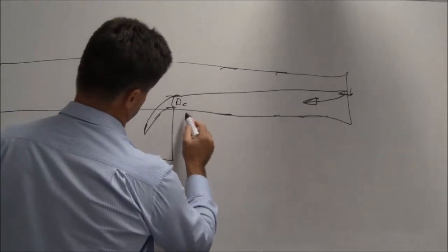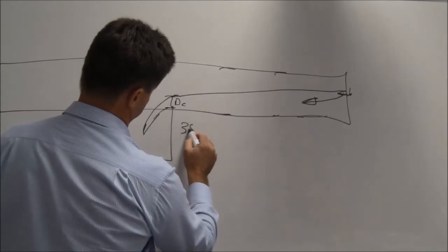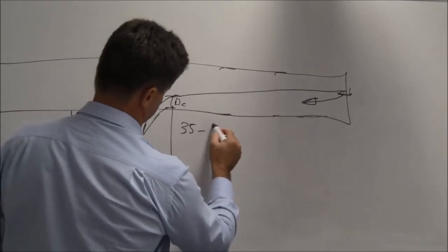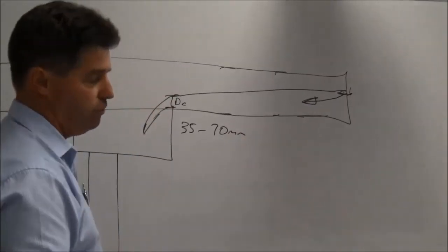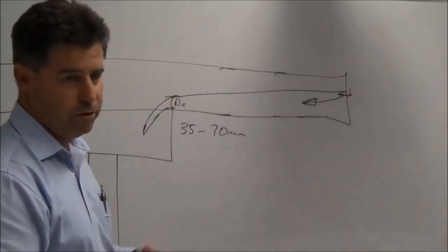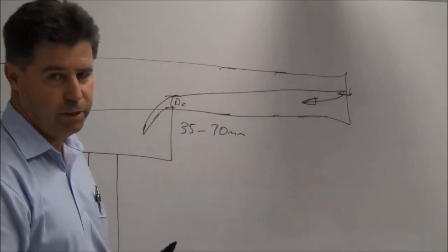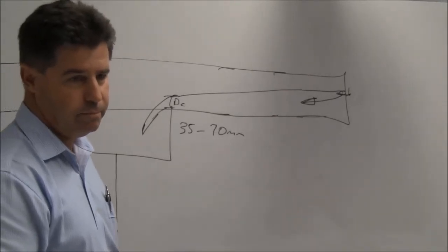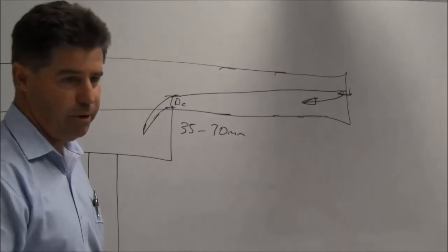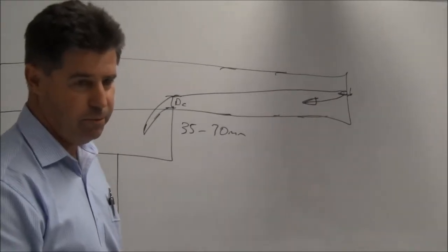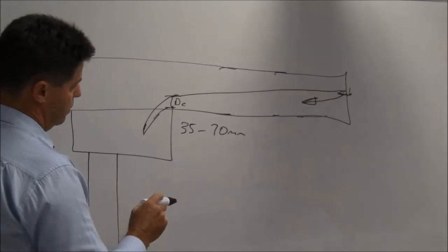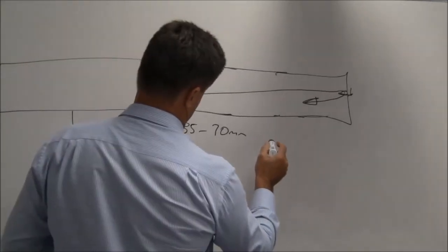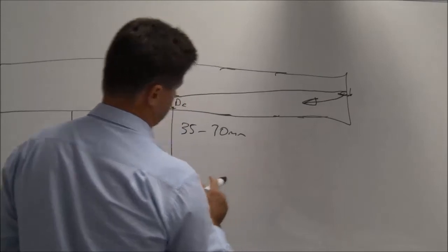So if you've got a height there of 35 mil, obviously it's 70 mil at the high end. Okay? Then we add our freeboard to the top of it to give you the total height of the gutter at that point. Yep? Obviously that wasn't an issue, or was that a problem? Okay. That was our initial height of 130 or 120 millimetres, yeah. Yep, so that's what you got, that's great.